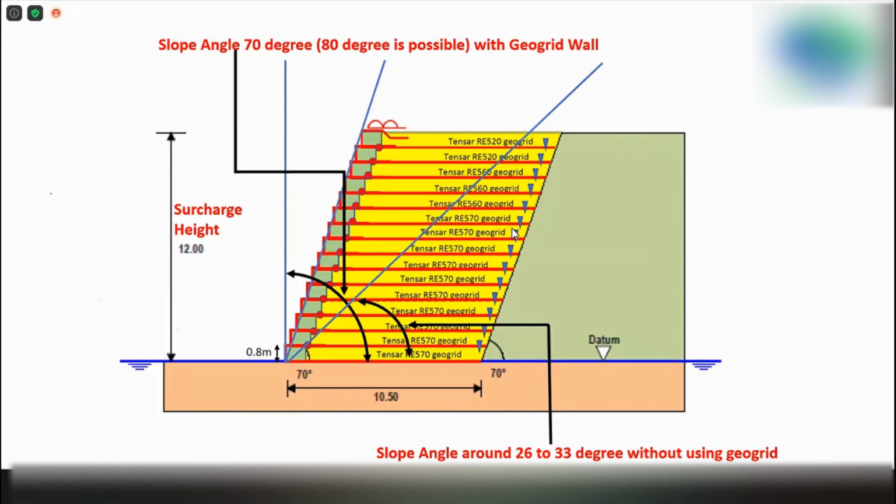So definitely you do not have the larger space of 24 meters. Therefore, by having this reinforcement, it basically solves that problem. You cut out the 24 meter space, it basically lets the slope stand almost vertically, close to vertical. We can have up to 70 degrees, and actually this is very effective for the PVD work, PVD surcharging work.